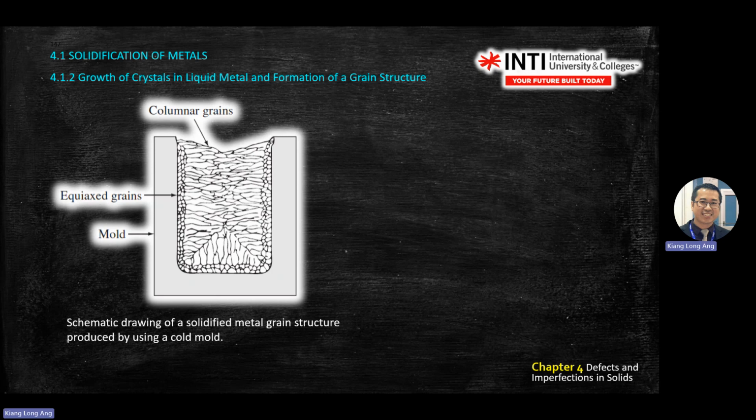But because of this already formed layer, the inside is still very hot. So the energy of the hot temperature must pass through this one, right? It must pass from the center to the wall. But this one is blocked already. So it will form a very long grain there. Then here already formed. So this will be the first layer formed. Then it will slowly cool down from here to here. It will take some time from here to here. It will form a very long grain.